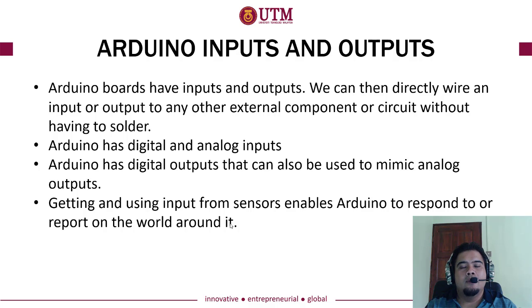So this change will be sent through the Arduino port, and you will detect that change if you develop code that reads the electrical signal change coming from that port. So of course, in order to do that, you need to assign the port of your Arduino as an input port, because it will accept any electrical signals from the outside. So that is one example of using the input port of your Arduino.